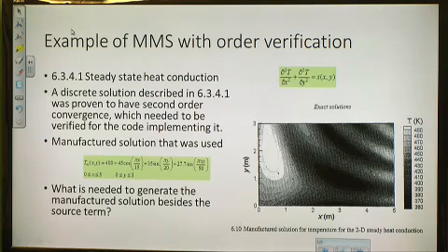If the code gives us the right answer, what do we care whether the order of convergence is what the theory tells us it should be? Because you don't want to run always with the finest mesh, so you need to do a convergence test. Say you want to get it to 95% accurate. You want to know that it's 95% accurate based on 2 tests.